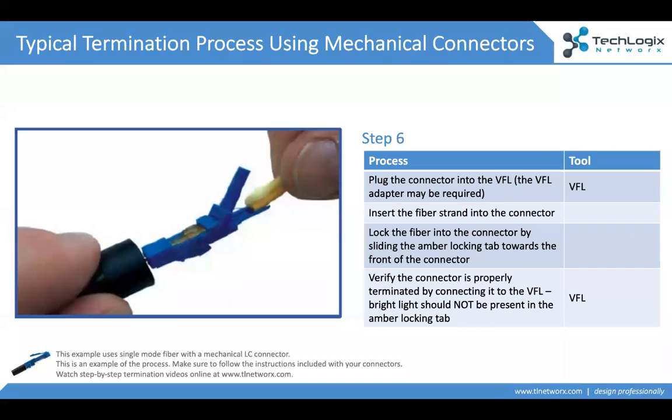And let's look at that process, because this is really the hardest part here, putting the fiber inside the connector. And the reason I say that this is the hardest part is because if you're going to break your strand, this is one of the places that it's fairly common to break the cable and then have to start over. Now, here's the nice thing. Most of these fiber optic connectors, they're reusable. So you can re-terminate, you can practice, you can reseat the fiber.